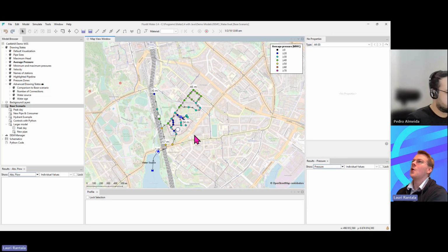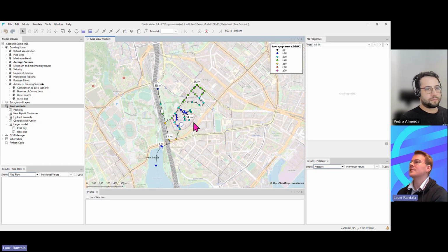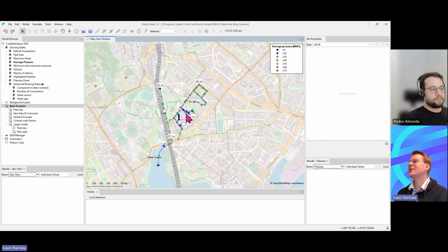Great point. Indeed. Most of the components are one-to-one to EPANET, as they come from there. But the pump battery is a Fluidit component, so to speak. The normal pump, which is exactly the same as in EPANET, will require you to have a pump curve, and it will then be driving on that specific curve that you have implemented, depending on the system curve, and of course, whatever flow is needed, then it will create that pressure there.